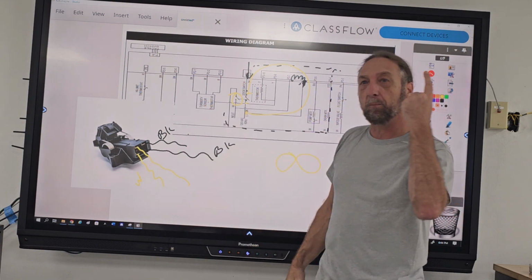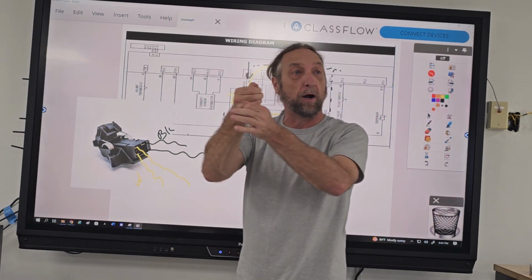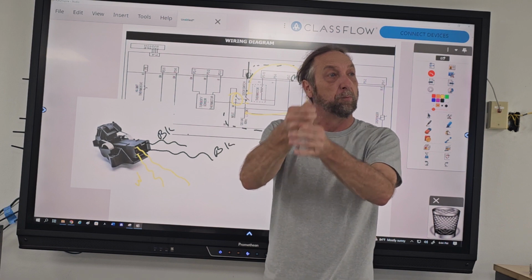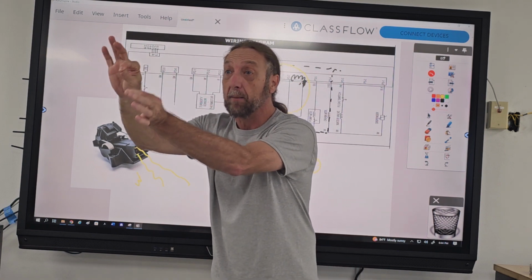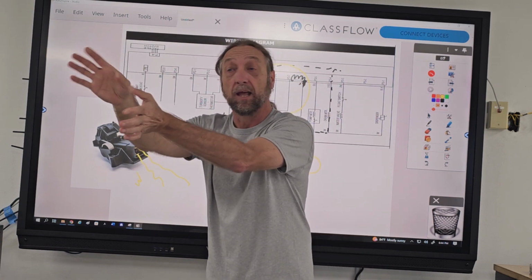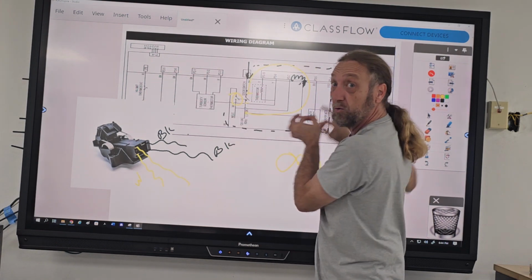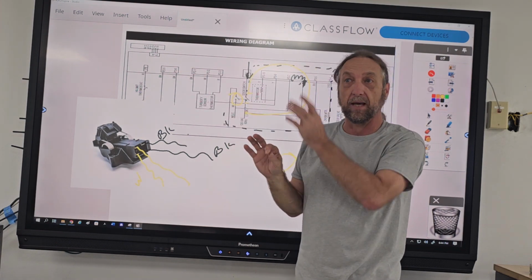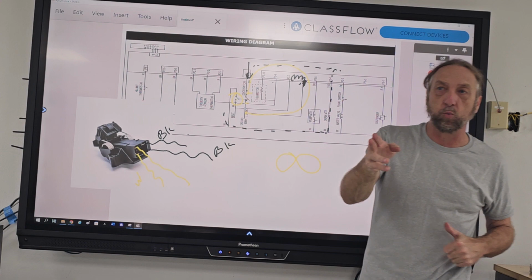So you at least have to pull one wire out of the 2 wires that are connected to a part to make sure that when your meter's on that part, that is what you're testing, and you're not reading through the wires back through something else in the machine. That's isolating. But there is one more thing you have to do.